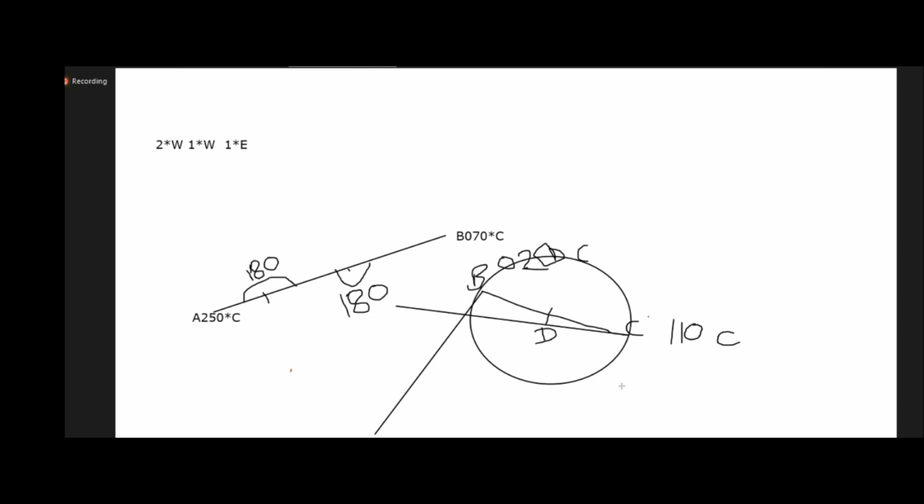Always the bearing is taken from the ship to the lighthouse, not the lighthouse to the ship. Your vessel may be somewhere here, heading like this. Heading can be anything, but you are standing here and from there you are taking it. Okay, fine?